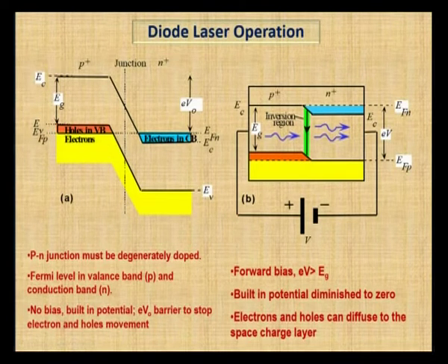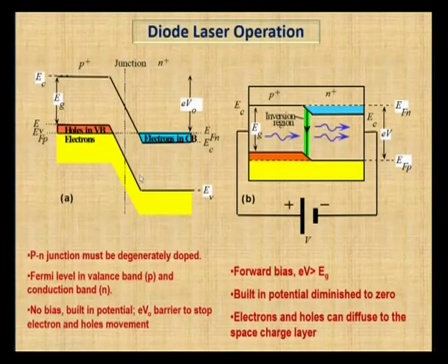With a potential or voltage equal to the potential barrier voltage, we can make the electrons flow from n to p. In forward bias, when the applied voltage eV is greater than the energy band gap Eg, conduction takes place, because the potential barrier is reduced and is almost 0.